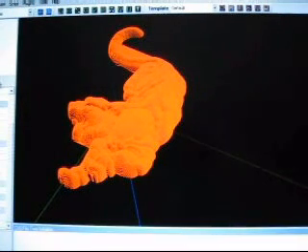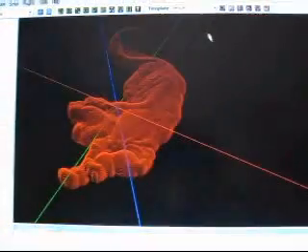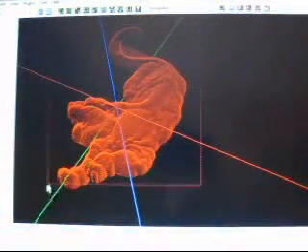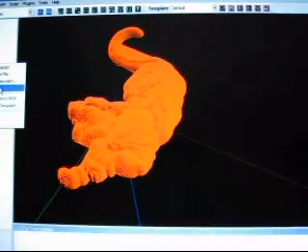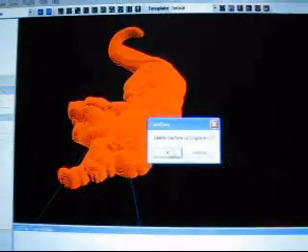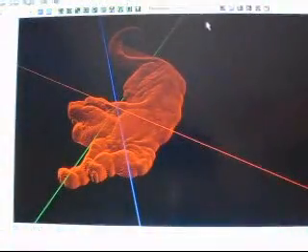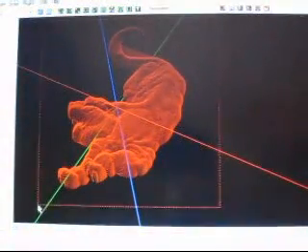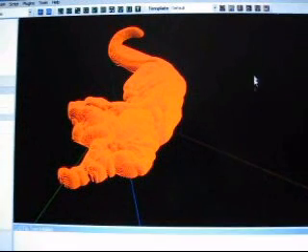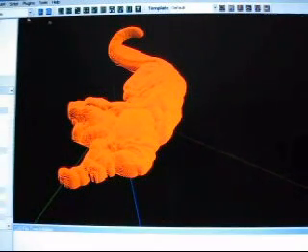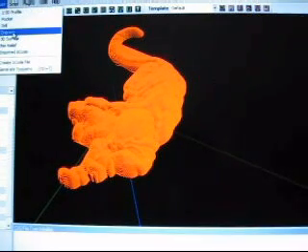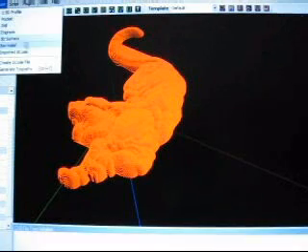So basically, here's how you do it. You're going to select everything. Here, I already wrote an engraving program, but I'll delete it. So we'll write another one. So, you select everything. You can hit it over here, or you can go Cam, Engrave over here. Either way, doesn't matter.